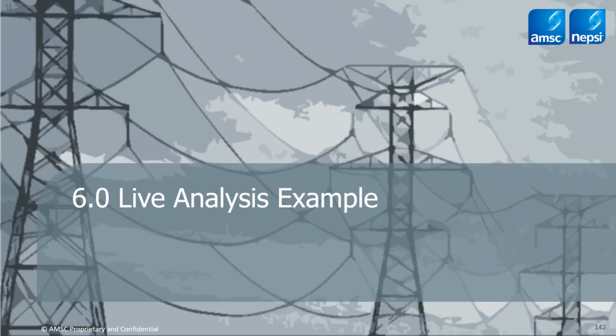Harmonic is like a steady state condition that we want to simulate and understand. Yes, it does vary slowly over time in most cases. Well, for arc furnaces, it varies quickly a lot, but we still analyze it from the AC perspective as something that is fairly long lasting, and it's not a subcycle transient condition. This covers steady state harmonic contributions.